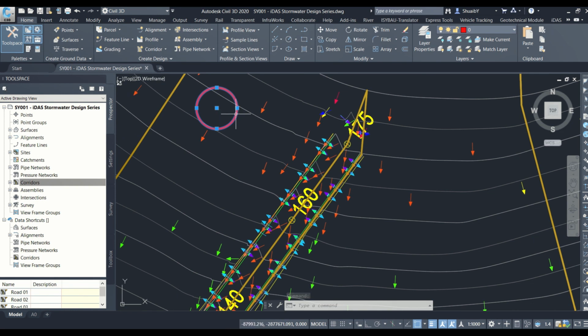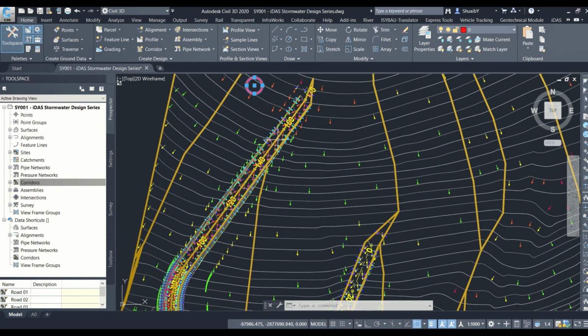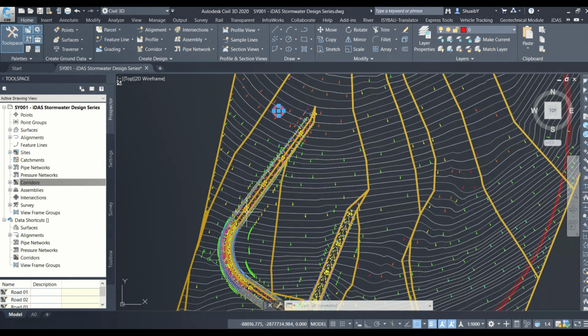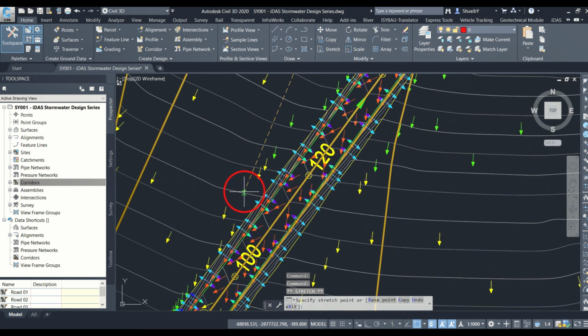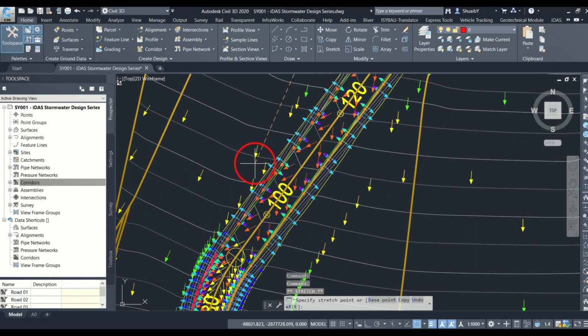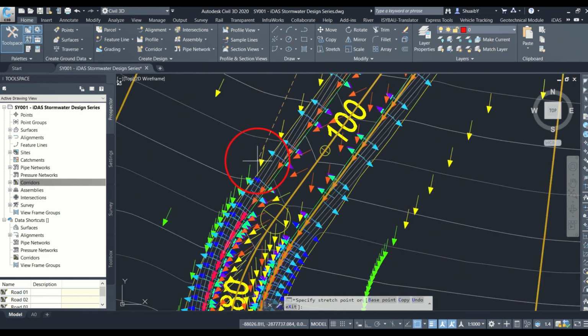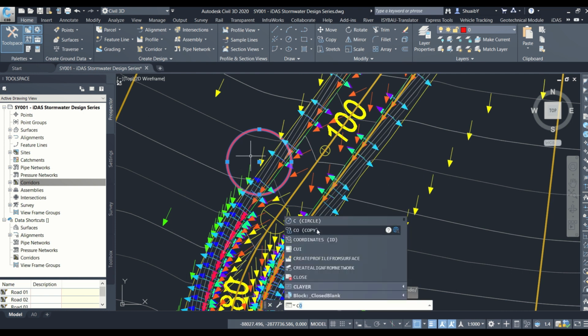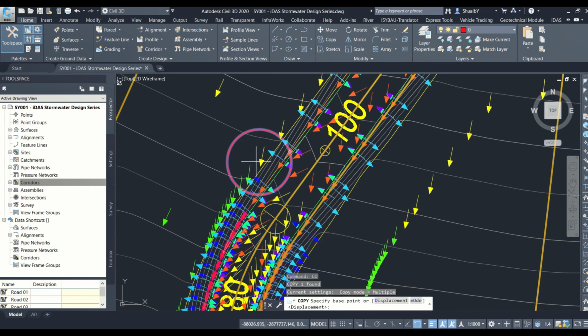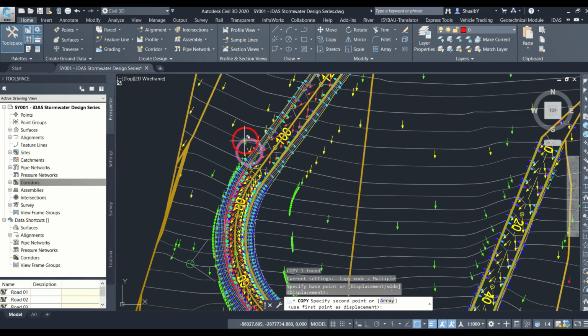And I'm going to copy this circle to the positions where I want to position a possible inlet for the road, where I think the curb inlet will be suited. Like for example here, you can see it's going to flow down the curbing channel, and we're going to come there. So we're going to need an inlet there before it actually reaches the curb below it. Right, so let's just copy, and this is the process or the methodology that I'm going to be applying.